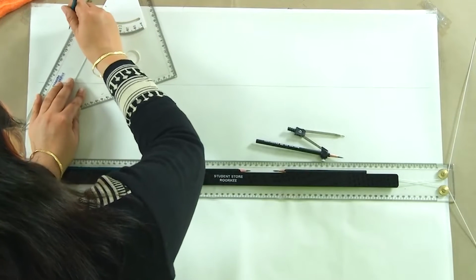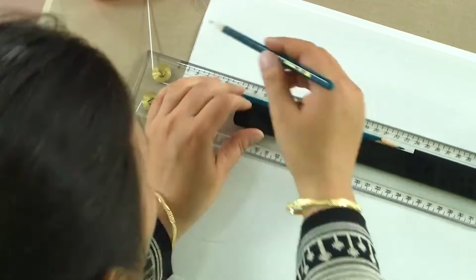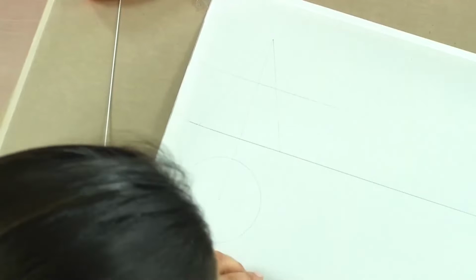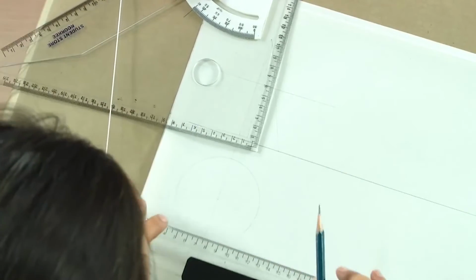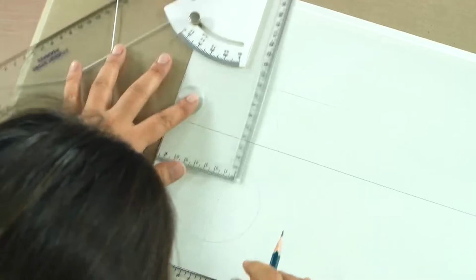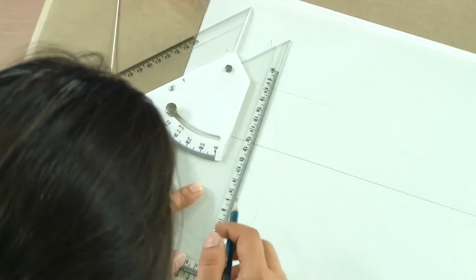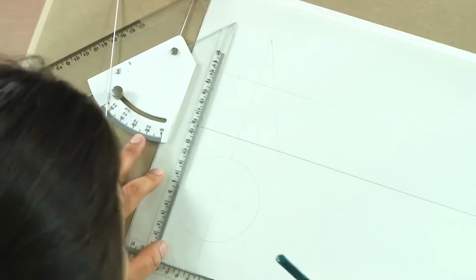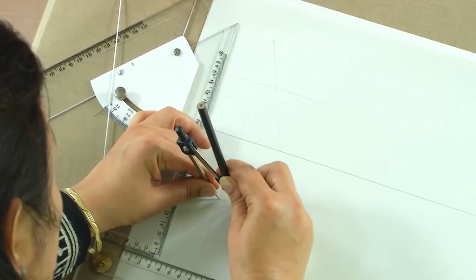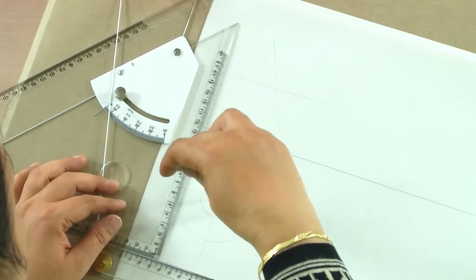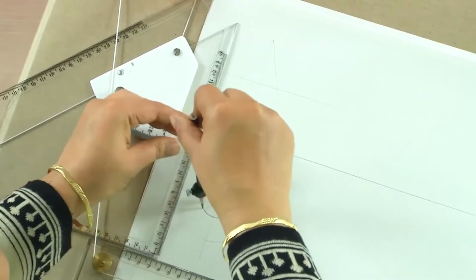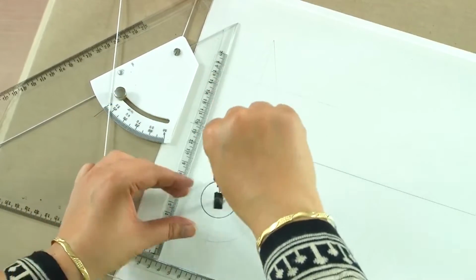So this is the original position of the cone which we are assuming, and we will take section planes at different conditions in this cone. Now in the first condition, let us assume that this cone is being cut by a section plane which is parallel to the base. So I have drawn a section plane here which is parallel to the base. Now in this case it is very simple. Simply if I connect this, I have a generator which is connecting these points, and since it is parallel, we will be getting to see a circle here at this distance from the apex. So this is what we will get in case the section plane is parallel to the base.